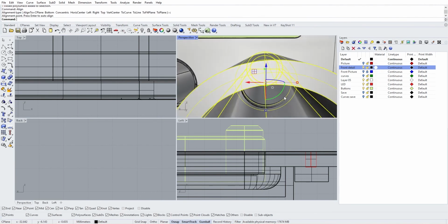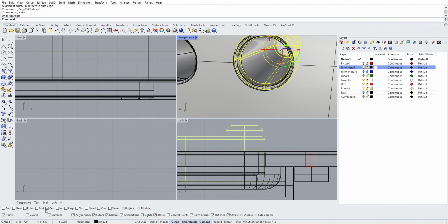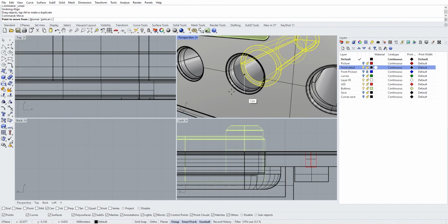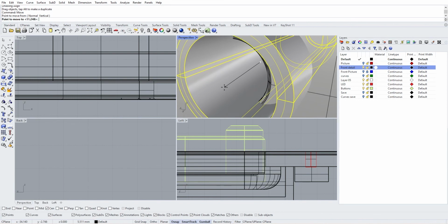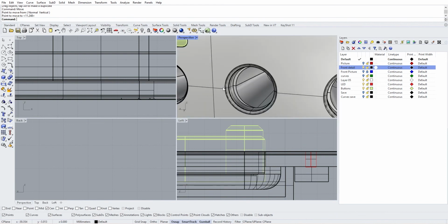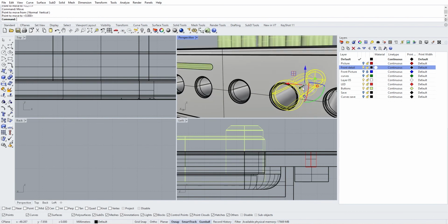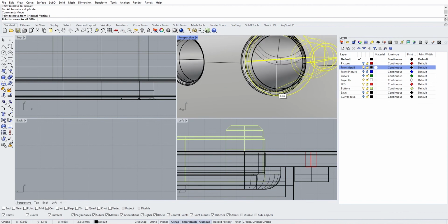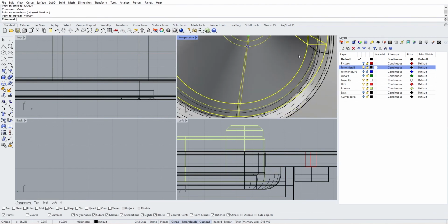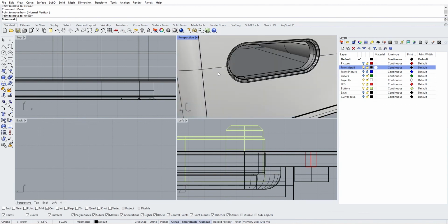So align, concentric, no. So maybe you can only select for the snapping tool the center, so that if you do the move tool, you can only select centers, so it will be easier to snap. Like this. Like this.